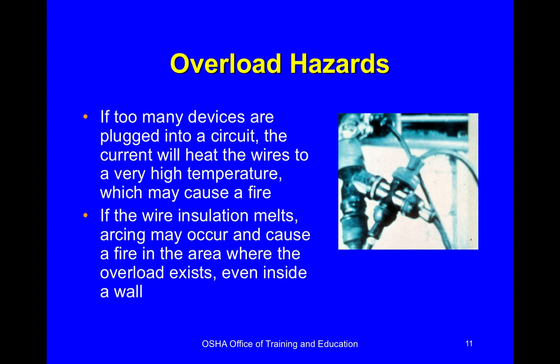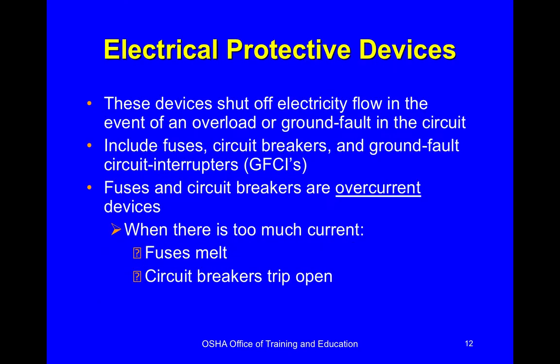Overloading. So if you plug too many things into one device, if you take a duplex, which is 2 outlets, and you put one of those multipliers on it that gives you 6 outlets, or you plug in a power strip, you have to be careful because you've allowed for the potential of drawing too much current. You actually have to do a little bit of math. See what you're plugging in, add up what the total draw is going to be, and make sure you're less than what that one device could give you. Again, if you're drawing too much, you're going to get heat. With the heat, you can start to melt insulation. You can start to have arcing happening, okay? And this is probably going to cause a fire.